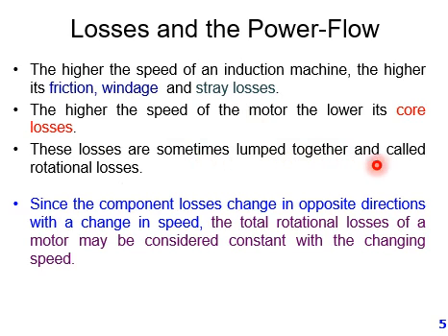Since the component losses change in opposite directions with a change in speed, the total rotational losses of a motor may be considered constant with changing speed.